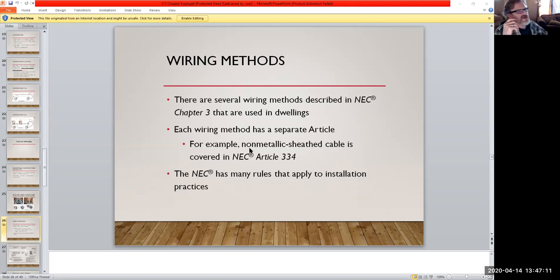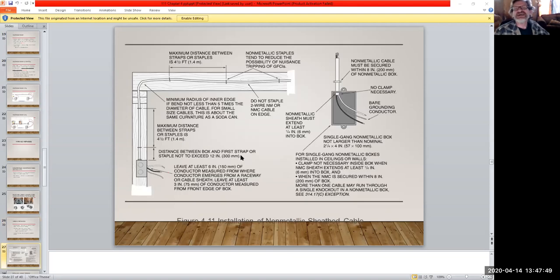And I think if you went through that article that I had you go through, you can see what would happen in a case where the electrician wasn't taking precautions with his sheath cable. And that's the drawback with that stuff. If you're running it in conduit, you typically don't have to worry about nails or screws coming into the wall and hitting stuff. But when you run the sheath cable, you got to really think about where it's being routed, because at some point, even if it's hanging a picture on the wall or something like that, people are going to be driving nails through the walls. It's to be expected. But we have some specifics, right?